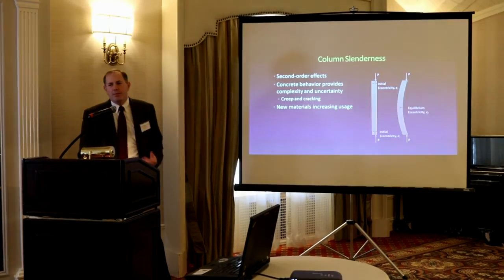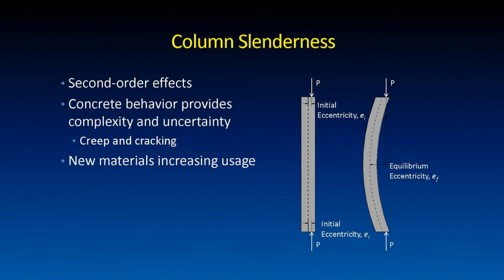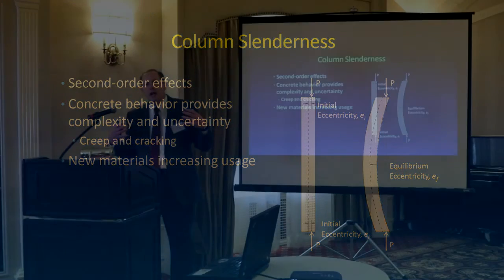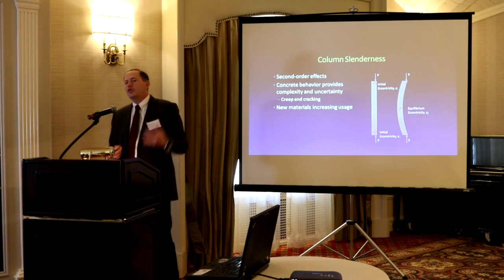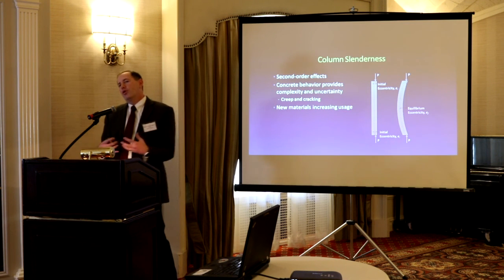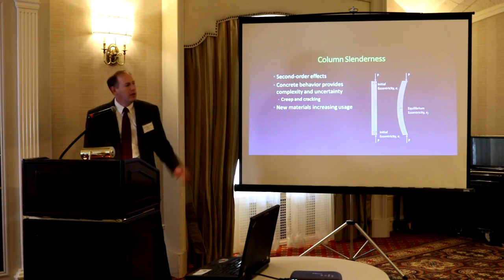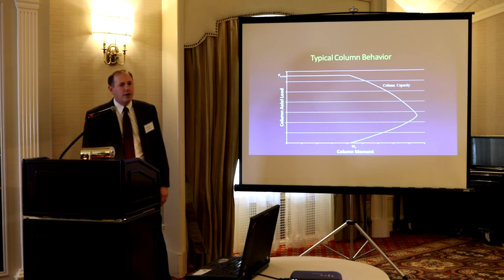And then what's happening right now is new materials. And this is not just something that happened today. I mean, we're looking at high-strength concretes that are approaching 15,000 psi readily used in construction, approaching 20,000 in some markets. So now with higher strength, we can decrease the size of the column, and then we go into the steel, and I saw we have some high-strength steel folks in the audience. Grade 100, I worked with Pankow Foundation, and we're trying to look at how we use Grade 100, maybe 120 ksi, and when we do those types of materials, that could also shrink the size of these columns and have more leasable square footage for developers, things like that. So there's definitely some interest in this area.